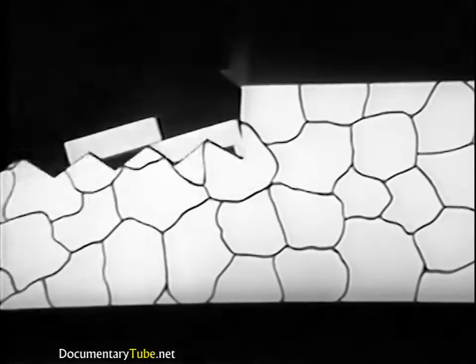It is by this process that the metal grains become elongated and uniformly oriented when an alloy is cold worked. Essentially the same action is involved in the plastic deformation of the polycrystalline grains composing an alloy specimen.